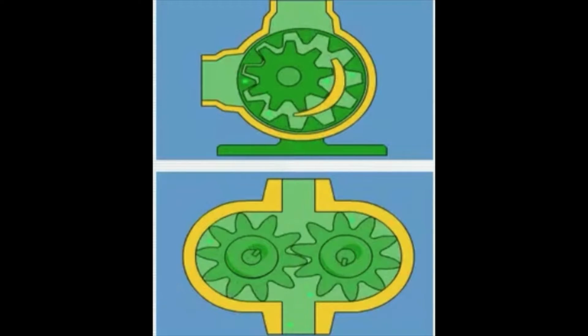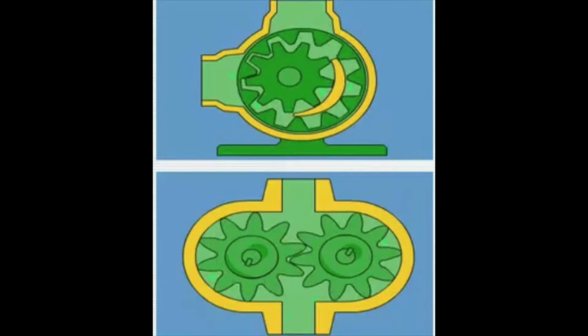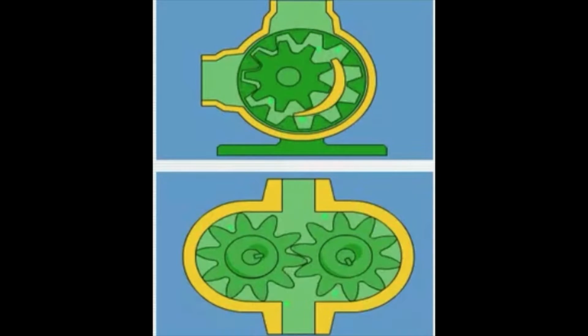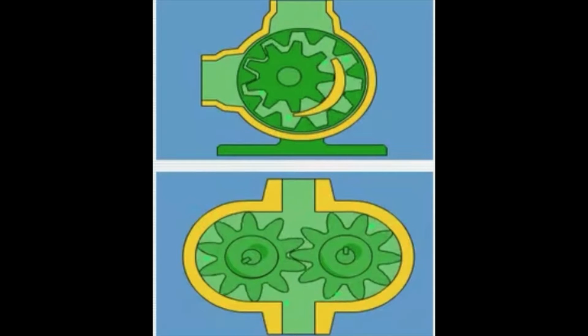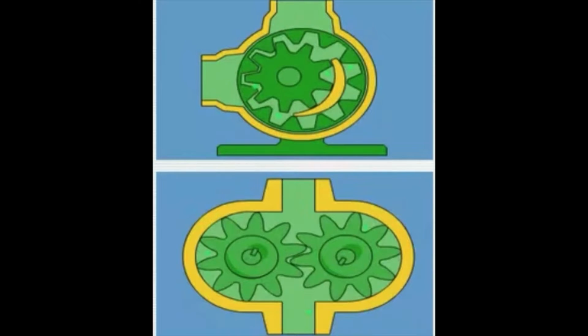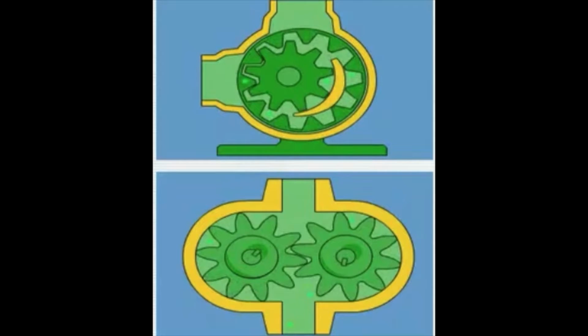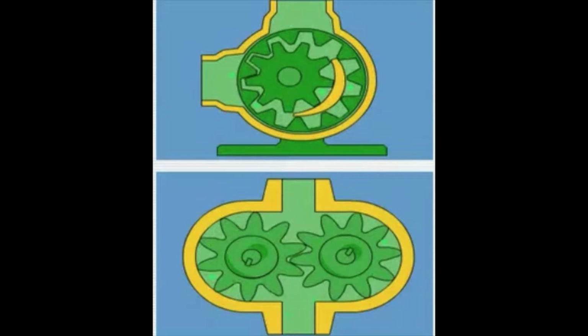These are rotary pumps. Rotary positive displacement pumps use pressure that is caused by gears in order to transfer the fluids. The rotation of the gears causes a suction effect that draws the water through the pipes, causing a consistent flow. The top pump is an internal gear pump.